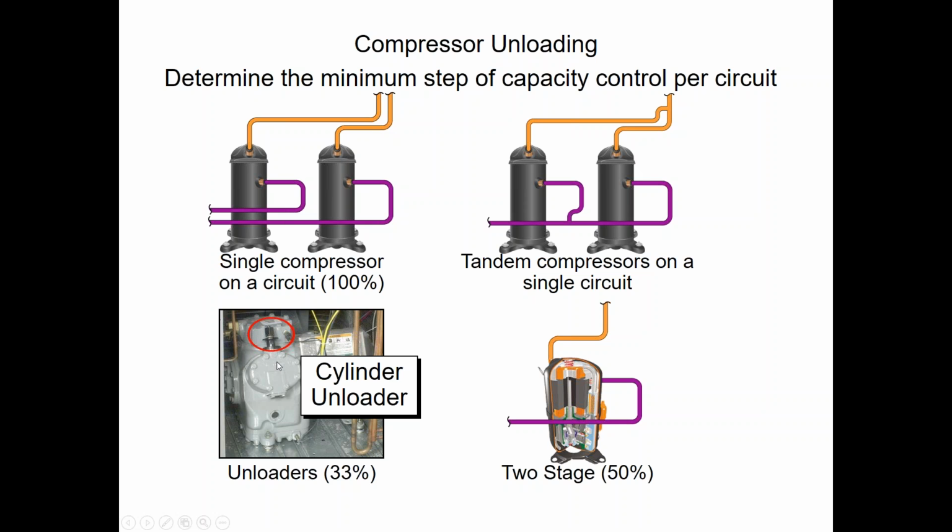If we have the old semi-hermetic compressors, we could have 1 head with an unloader. We could have 2 heads with an unloader if it's a 3-head machine. So this takes off 33% of the capacity. The other head takes off 33% of the capacity. Now we're left with 33% on the center head, actually trying to return the refrigerant gas through the suction. And at that point, the piping would be oversized. So again, that drives you to look at your verticals and if we need speed risers or double suction risers.